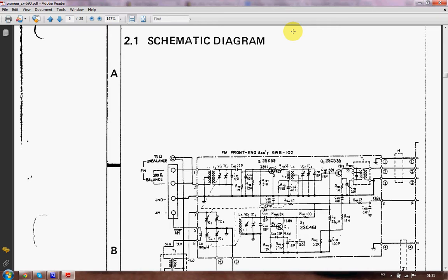So guess what it would look like if you put an oscilloscope to a direct current voltage. The baseline would just rise. So instead of having 0 volts, you would have, for instance, 3 volts, and it would be a straight line, which wouldn't drop again before you broke the circuit, and then you would have 0 volts again. So you would just raise the baseline. So you don't need to use the oscilloscope where you expect direct current.